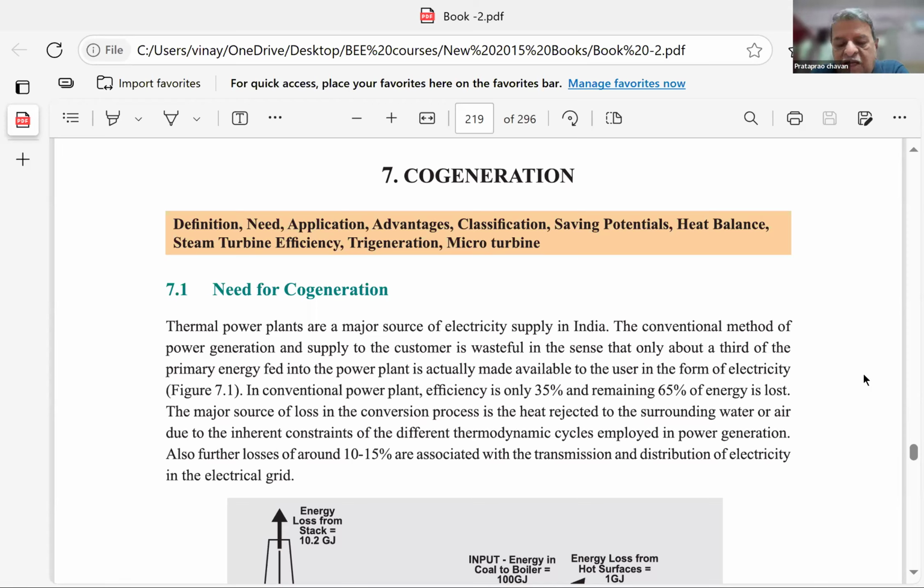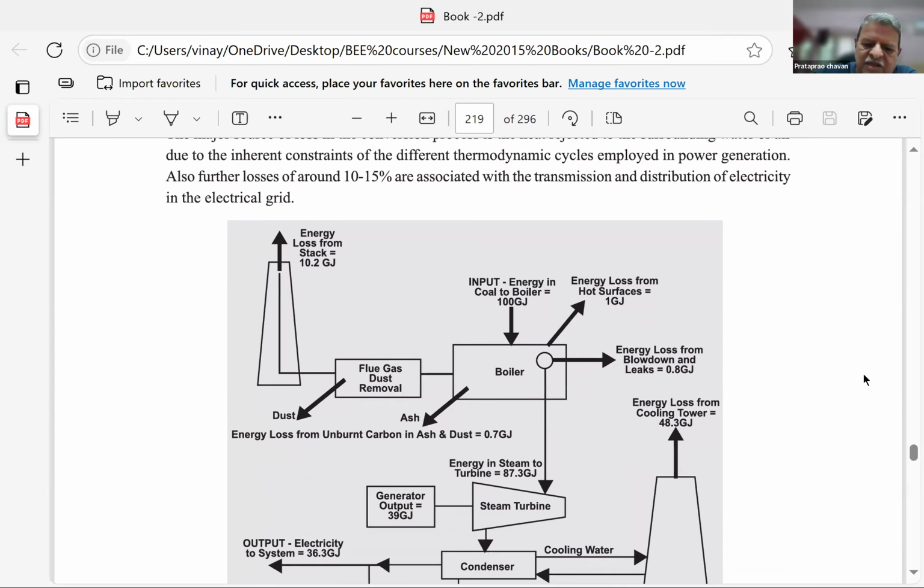If you do this, again it's a cogeneration. Your main generation product is heat and you have also generated electricity. So sometimes fresh steam is used for electricity generation, and after that it goes as a heat source for the process heat requirements. So that is also a cogeneration, right? So you know what is cogeneration: simultaneous generation.